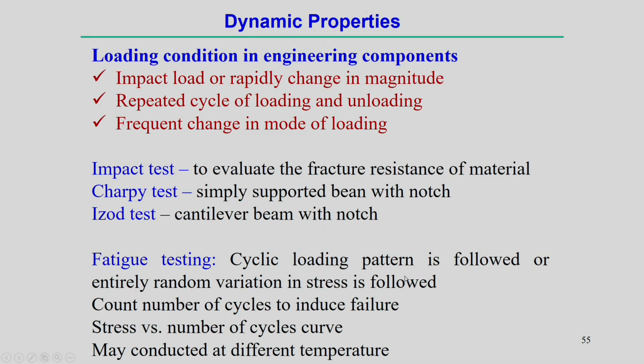And then with static loading conditions we can evaluate all the properties, but dynamic properties can also be measured, mainly through the application of dynamic load. First, in what way can we represent the dynamic loading condition? One is maybe an impact load, or load applied in such a way that there is a rapid change in the magnitude, quickly there is a change in the magnitude. That is one case.